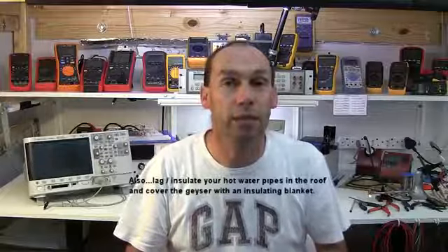If, however, your water is sitting at 65 degrees, it's going to pull slightly less hot water and start blending cold. If your water is sitting at 70 or 80 or 90 degrees, it's going to pull far less hot water, and it's going to be blending more cold water to give you that 55 degree water coming out. And that means you start saving water in your geyser because it's at a higher temperature. So it's certainly something to note. In other countries, if it isn't legislated, look into installing a thermostatic valve or a tempering valve for that functionality. It really makes a big difference.